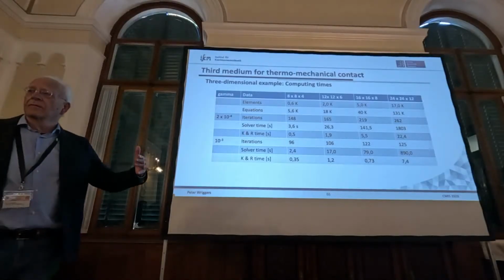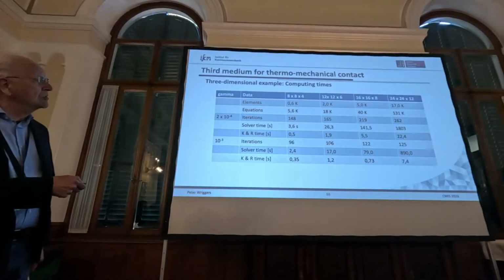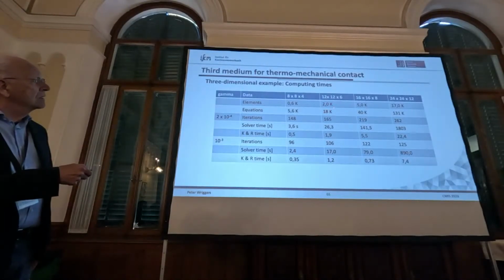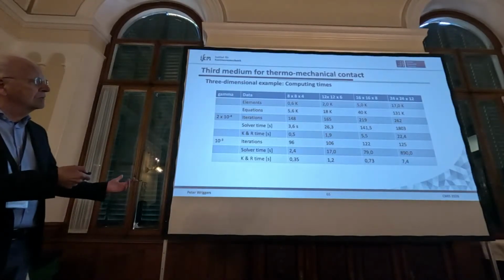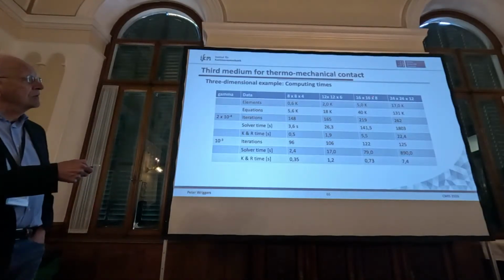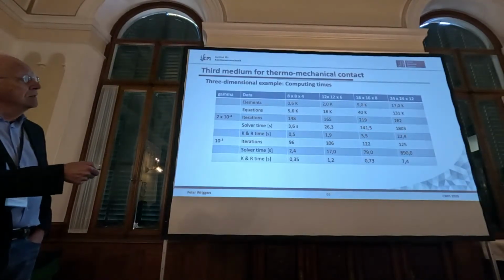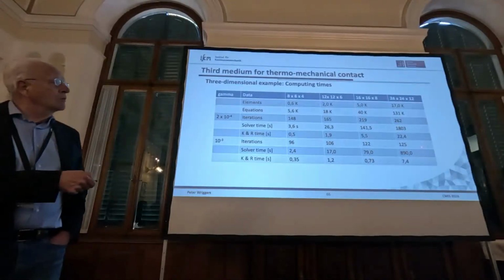So this is manageable. And if you get a larger mesh, 12 by 12 by 12, you have 2,000 elements, 18,000 unknowns. So we are talking here about 30 seconds for the solution. If you have a 16 by 16, it's still working fine. So it's about 2 minutes, 3 minutes to run. If you are at 24 by 24, of course, you get caught by the solver.